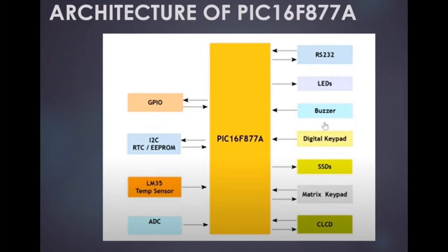PIC microcontroller is used in this project. PIC microcontroller is the RISC processor. It has separate code and data memory spaces. It has flash program memory, SRAM, and EEPROM data memory. It is a 40-pin DIP and it has 15 interrupts.